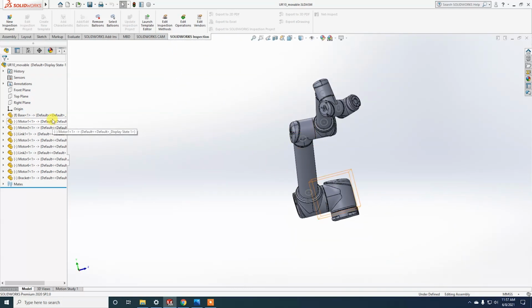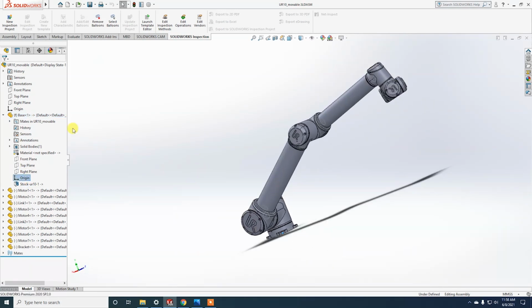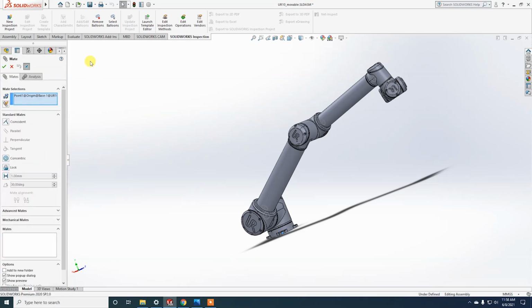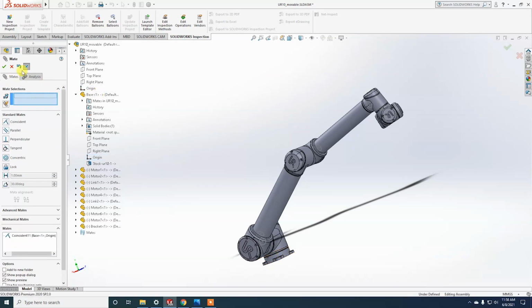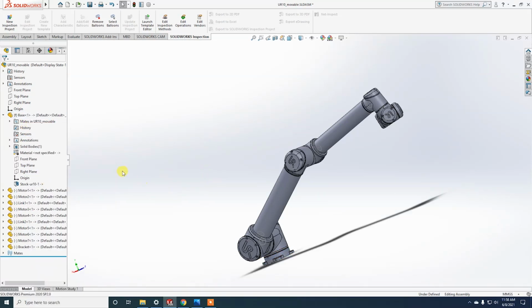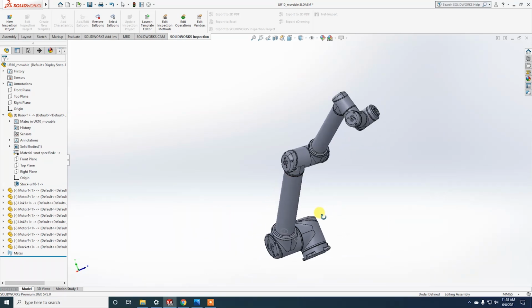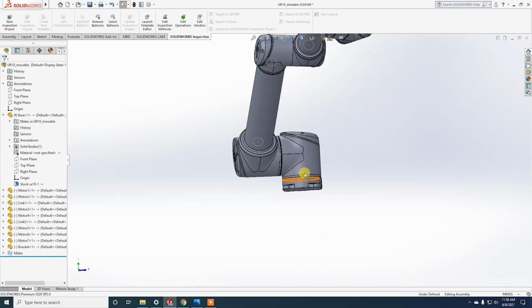So the first thing is that this is a fixed point joint, and the problem with this one is that this origin and this origin are not the same. First of all, I want to make it float and then mate, and let's make this one similar, then press OK, close, and now I'm going to make it fixed. So now this is fixed. Basically, to convert this file for ROS and Gazebo, we need to define the correct axis of motion and coordinates.